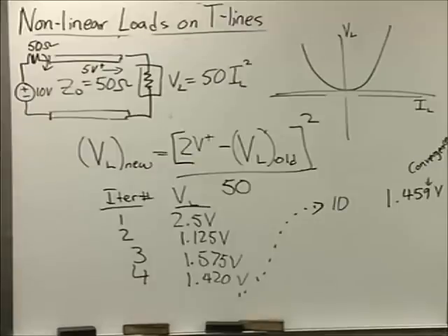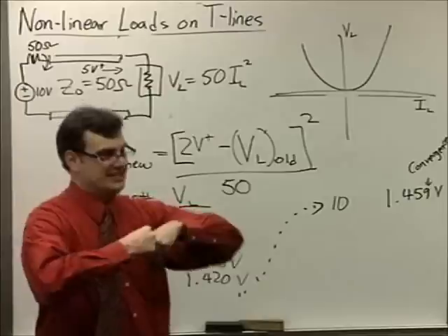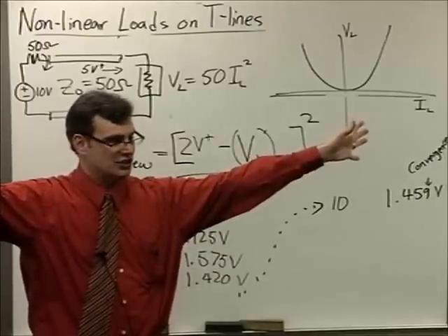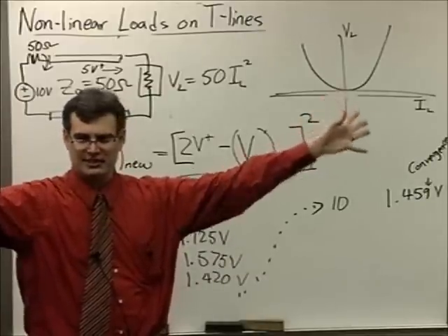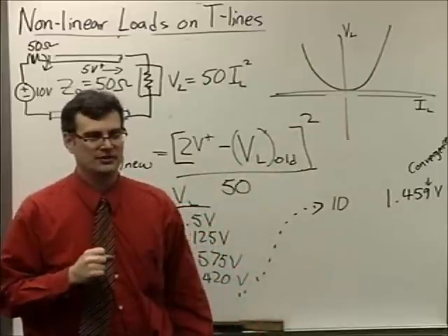You keep running it, and one of two things is going to happen. It's going to converge, and the answers aren't going to change anymore when you set up your equation. Or it's going to diverge, and you should solve it with respect to currents instead of voltages. You just rearrange the same equation, have it with respect to current instead of voltages.